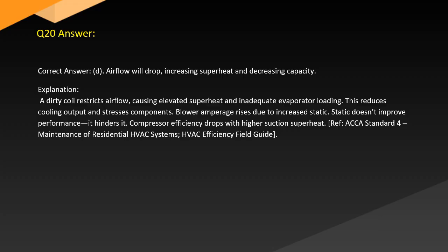Static doesn't improve performance. It hinders it. Compressor efficiency drops with higher suction superheat. Ref. ACCA standard for maintenance of residential HVAC systems. HVAC efficiency field guide.